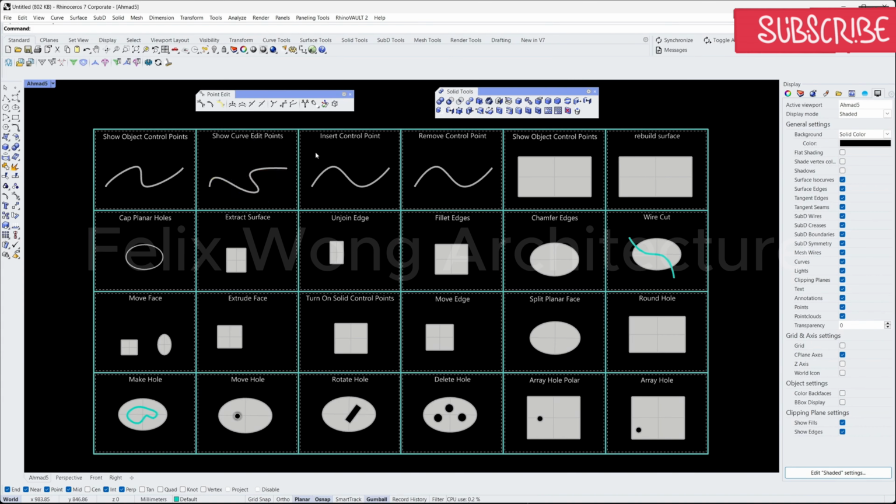We can add more control points to the curve by using the Insert Control Point command. To delete a control point in the curve, choose Remove Control Point, select the curve, press Enter.